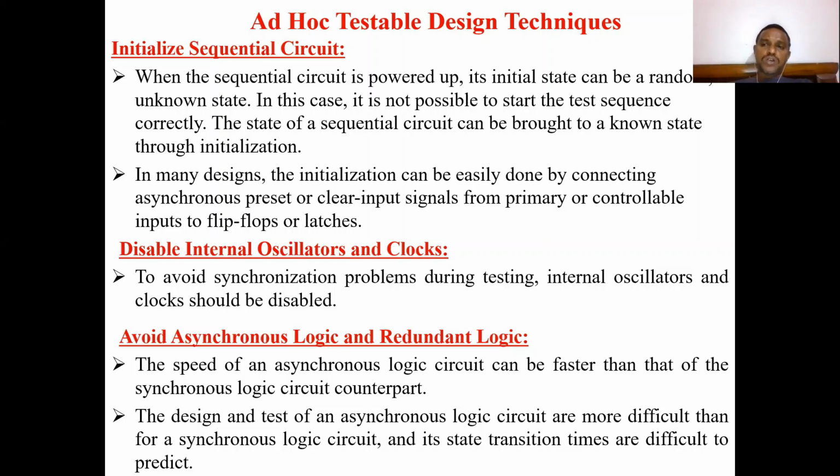If you want to test an asynchronous logic circuit, we cannot predict its transition times due to its speed of operation. The design and test of an asynchronous logic circuit are more difficult than for a synchronous logic circuit, and its state transition times are difficult to predict.